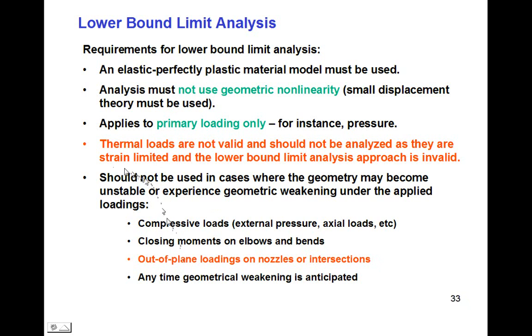It is stated that thermal loads are not valid and should not be analyzed, as they are strain limited and the lower bound limit approach is invalid. Although again, we have to go back to the large deflection, excessive elastic energy piping model and decide if this is truly the case for that. But again, the answer is always elastic plastic finite element analysis.